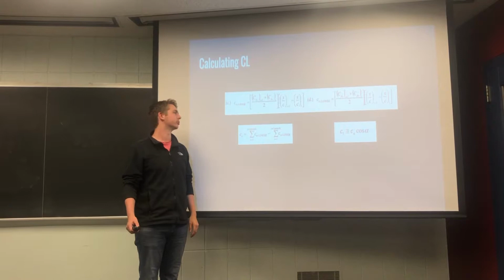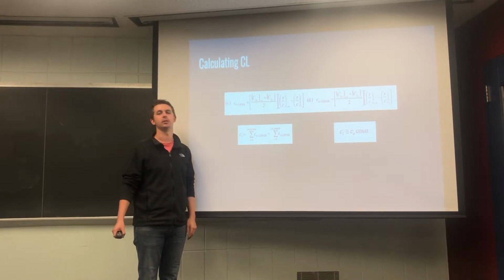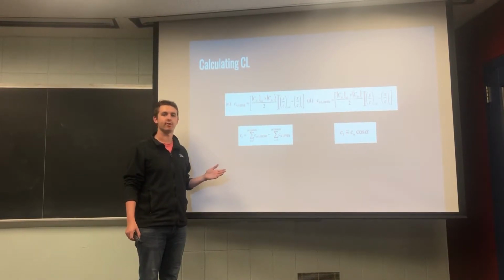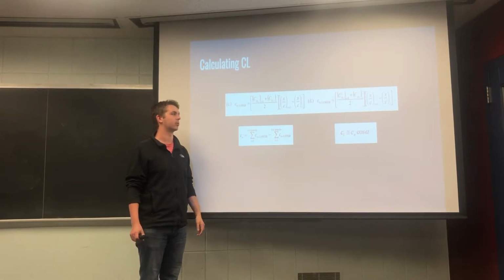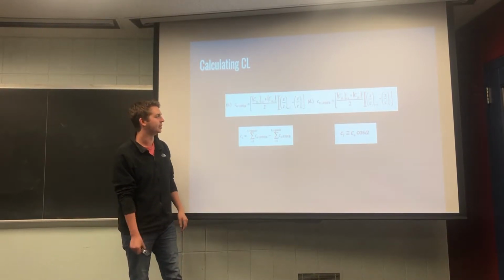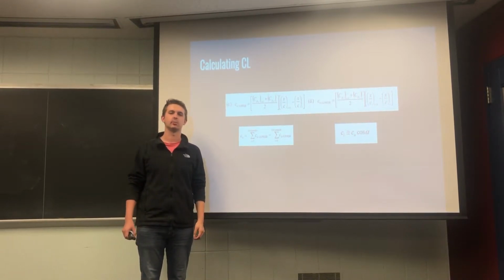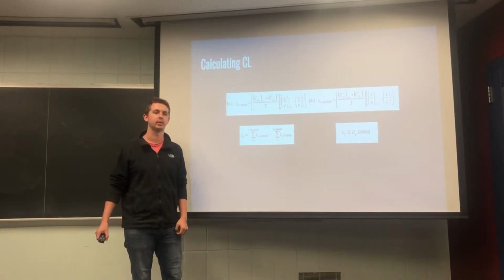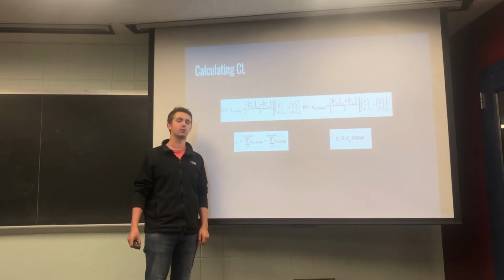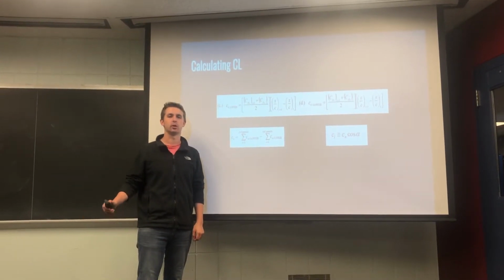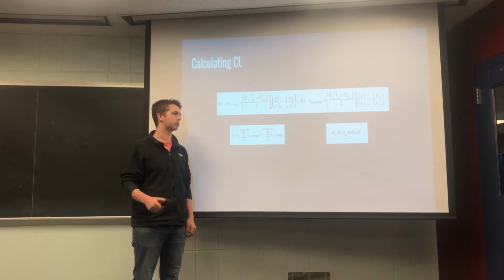Now our group had to find a Cn for every angle of attack, so these various CP and Cn upper and lower values had to be found for all of them. Now finally, CL can be calculated knowing that CL is equal to Cn times cosine alpha, where alpha is the specific angle of attack that was measured and recorded through a digital display.